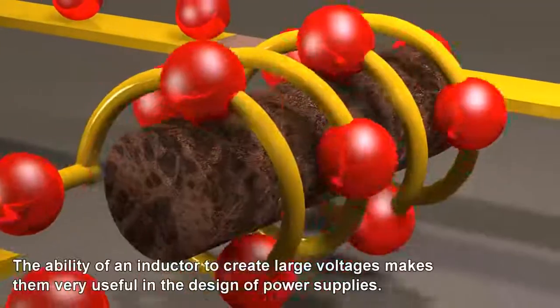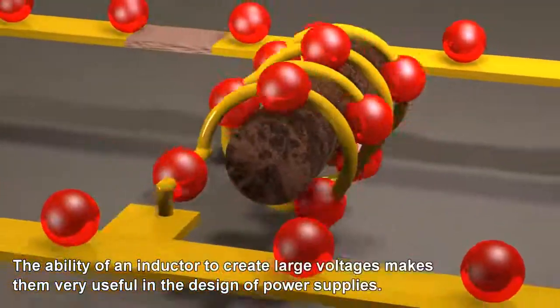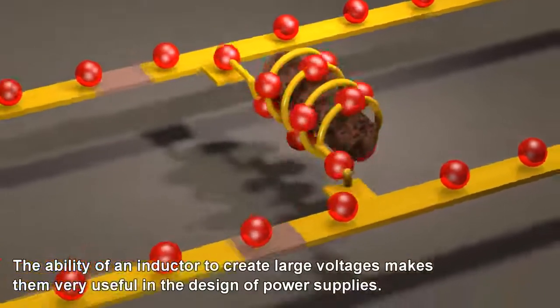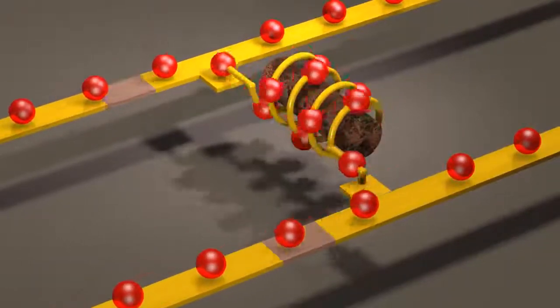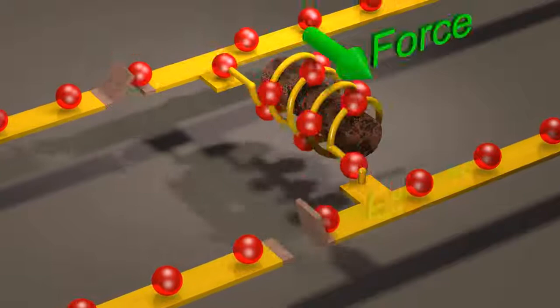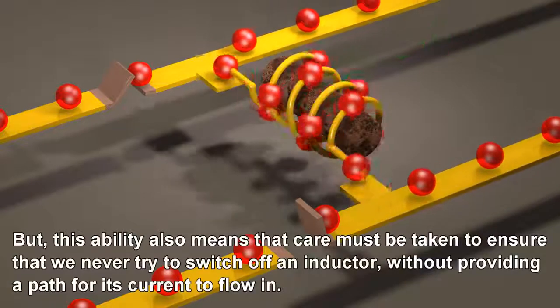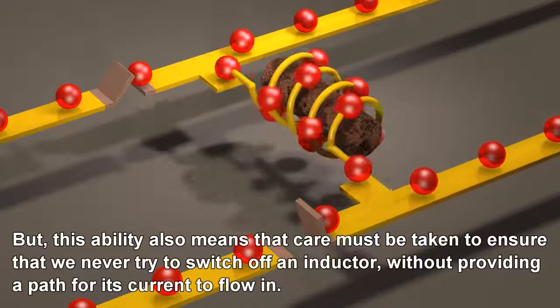The ability of an inductor to create large voltages makes them very useful in the design of power supplies. But this ability also means that care must be taken to ensure that we never try to switch off an inductor without providing a path for its current to flow in.